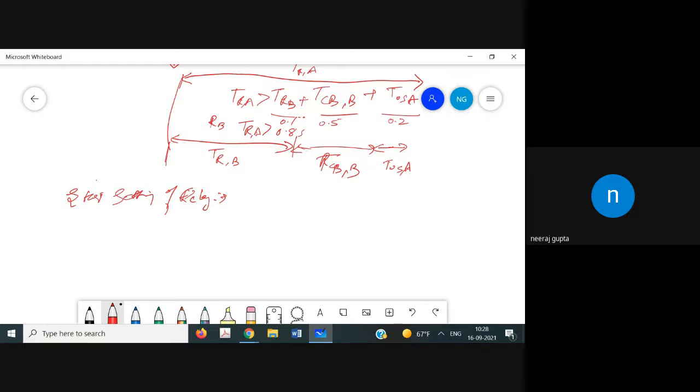So we can say the time step between the operating times of two relays, which is equal to the sum of the circuit breaker time and the overshoot time of relay A, is essential for maintaining the selectivity between these relays.